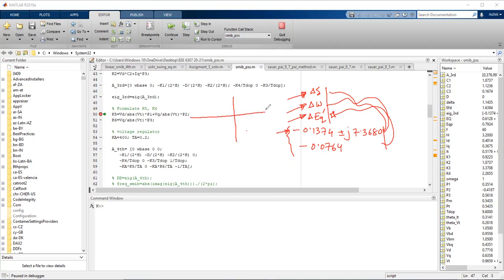Let's say among these three, which of the eigenvalues is the closest to the y-axis? The third one, because this is the negative. Look at the negative real part. This is minus 0.13. So probably this is somewhere here. Minus 0.1374 plus minus j, so this is a complex pair. But this one, you see, minus 0.07. So the distance from the y-axis is almost half. So this is lying here. So this is the dominant eigenvalue. This is nearest to the y-axis in the S-plane.